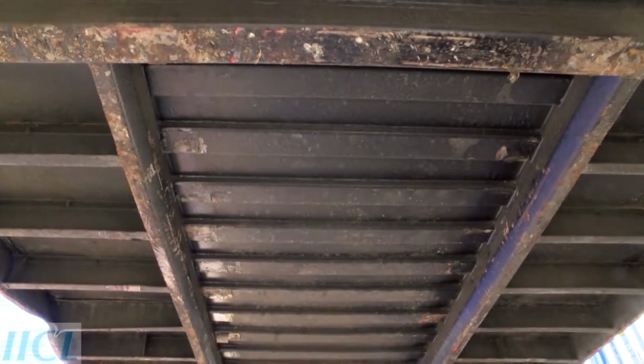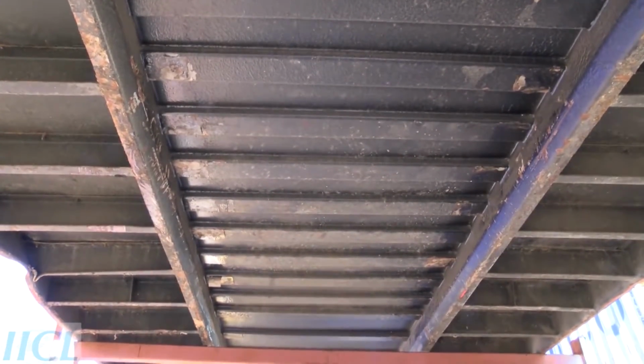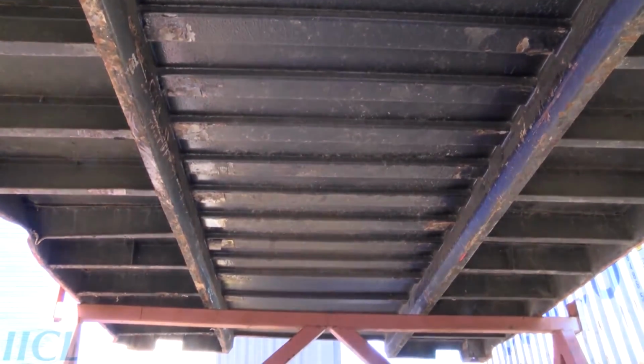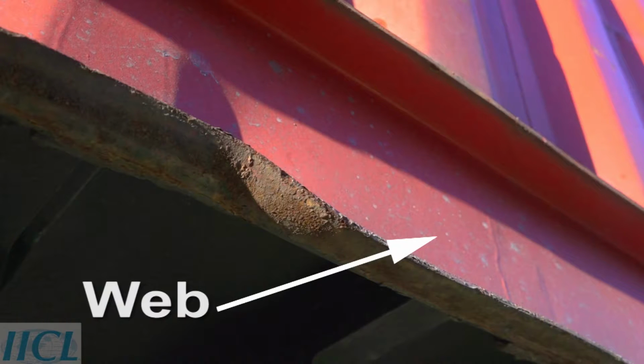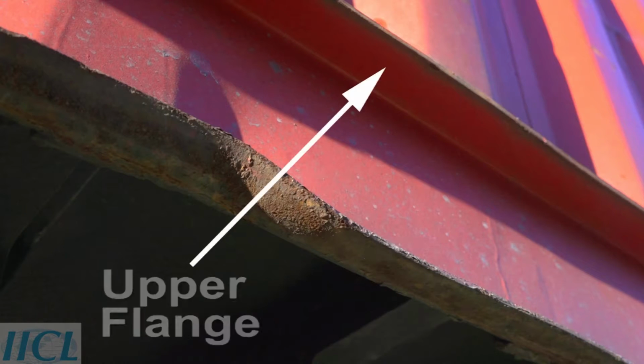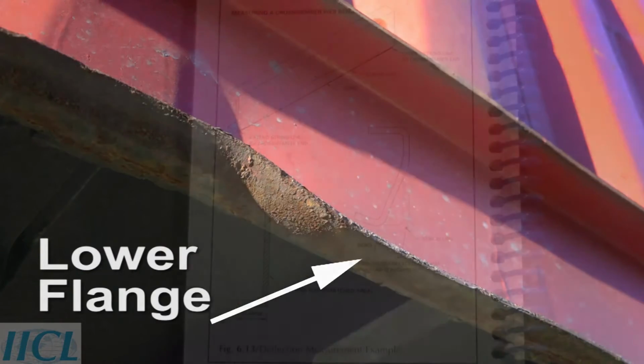Many of the container's understructure components are C-shaped channels, and the IICL specifies inspection criteria based on what part of the C is damaged, the web or the flanges. The web is the vertical part of the component extending from the center of the bottom bend radius to the center of the upper bend radius. The upper horizontal part is the upper flange, and the lower horizontal part is the lower flange.